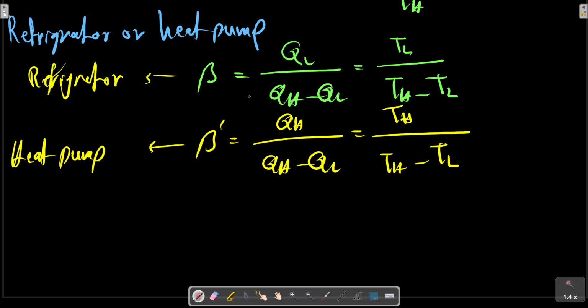For all three efficiencies stated before, the first equality sign is the definition with the use of the energy equation and thus is always true. The second equality is valid only if the cycle is reversible, that is a Carnot cycle, and real engines, refrigerators or heat pumps will be less efficient.